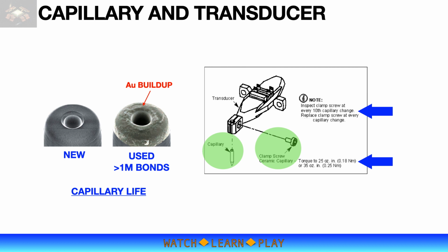The life limit can be from the equipment vendor or from a study done by the process owner. Just to caution, a clamp screw may look like just a regular screw, but its quality is critical. Do not use a cheap screw just to have a cost reduction project. Follow supplier recommendation if there's any, or buy from a reputable company that will provide you consistent material quality.